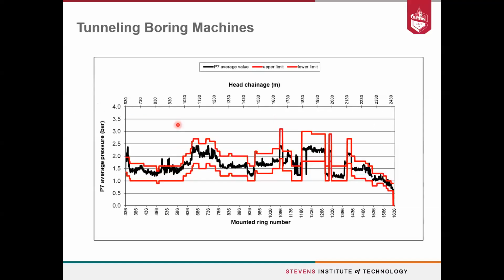So based on the ground profiles that I show you that are determined during the design phase, thresholds for the TBM operational parameters are set for different zones of the drive of homogeneous ground conditions. These thresholds are upper and lower levels of several main parameters, and what the operator must do is try to maintain the pressures and some of the operational parameters within those set thresholds.